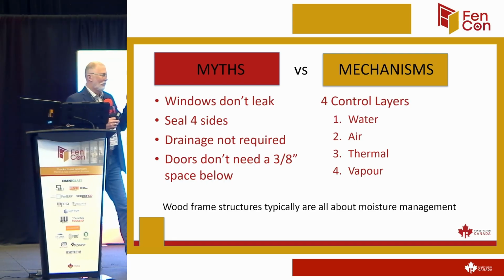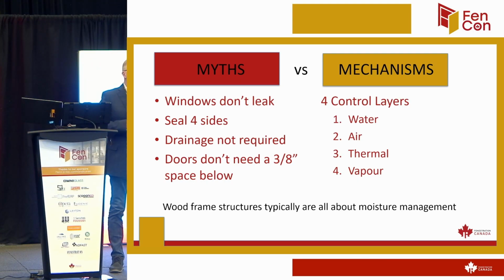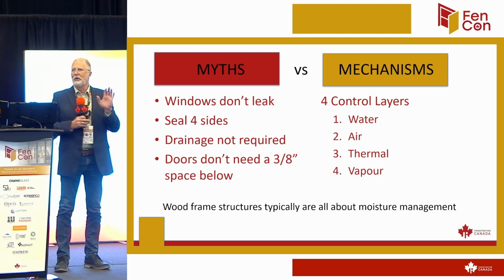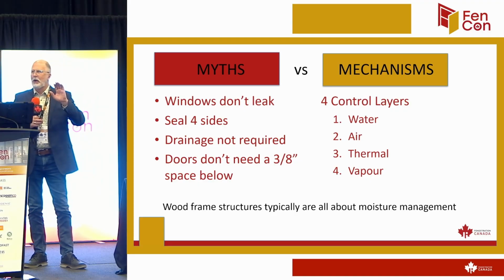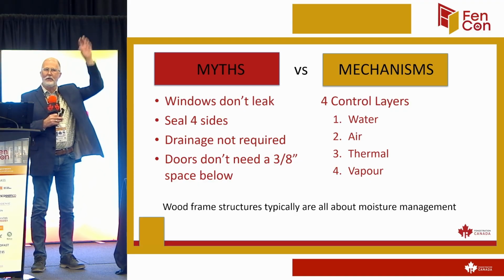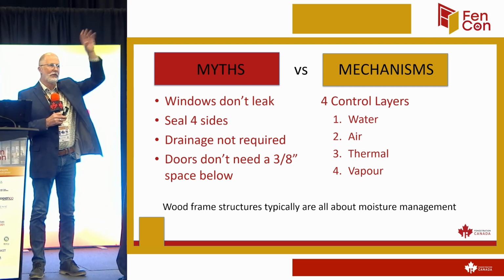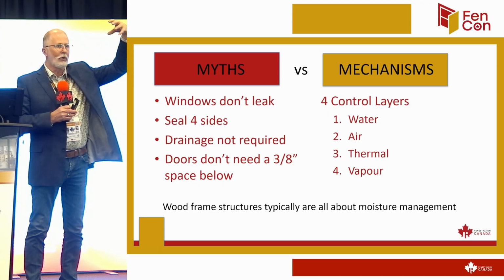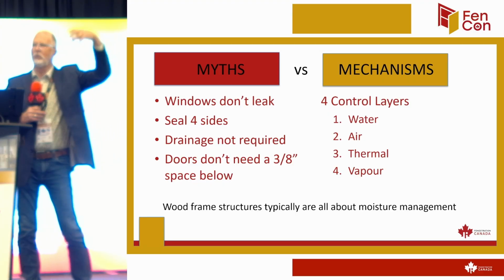I ran an envelope engineering company, and we would test windows. What we found was that probably over 55% of the leaks in windows actually came from another source. It came in the soffits, it came in the upper window, it came in from a deck, it came from somewhere else, and it just showed up on the window below.